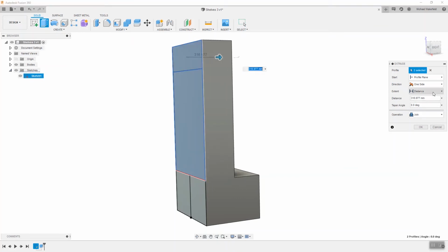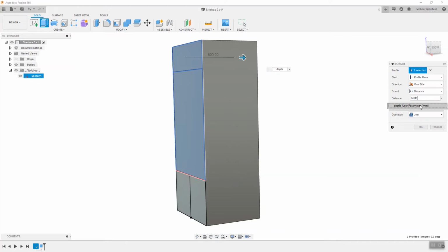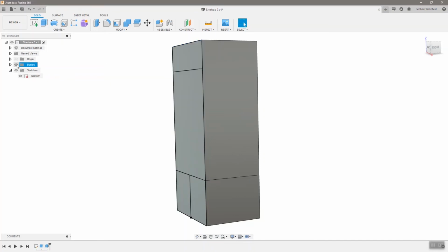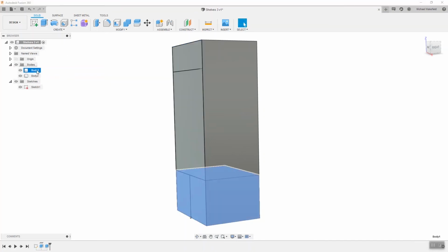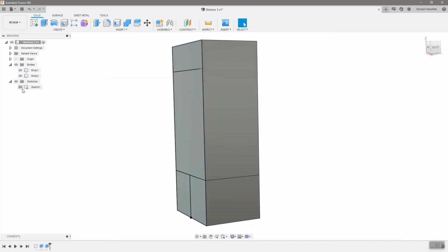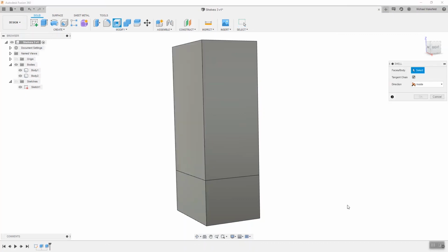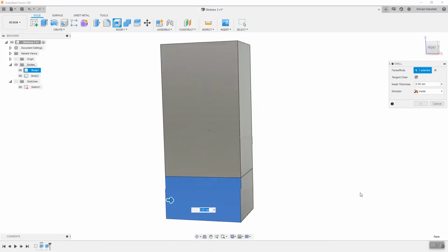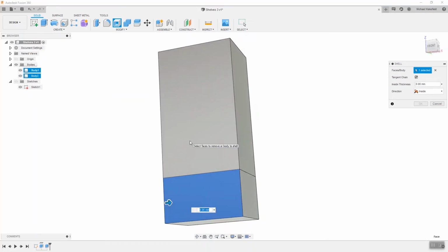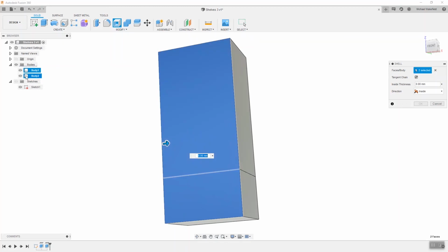And I did the same thing for the top, and I again used the parameter of depth, which was previously defined, and it's really important here that I create a new body so that this new body does not join to the body that was previously created. And I have 2 separate entities, if you wish, in my assembly. Now you have to keep in mind that this is not truly an assembly. It is still one part with 2 different bodies. That is not the same thing as saying it's an assembly with 2 different parts, and more on that later.